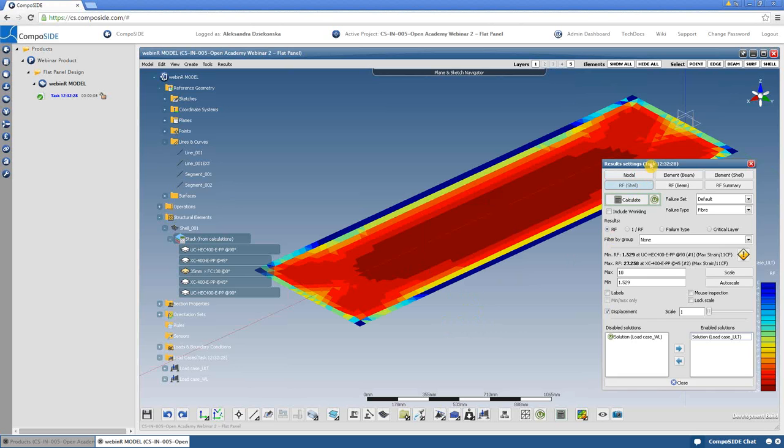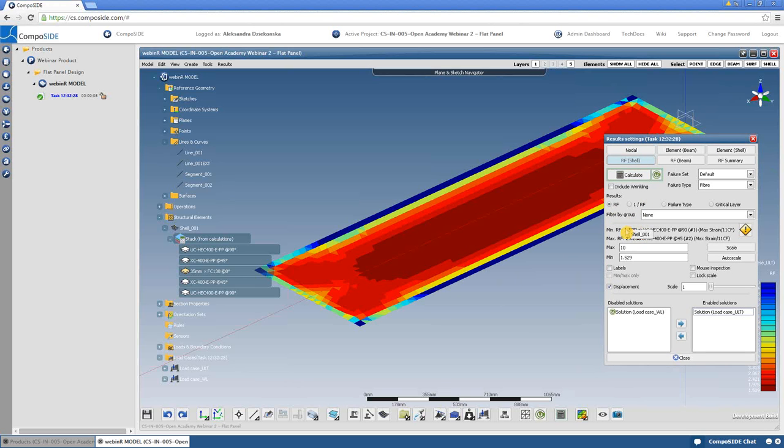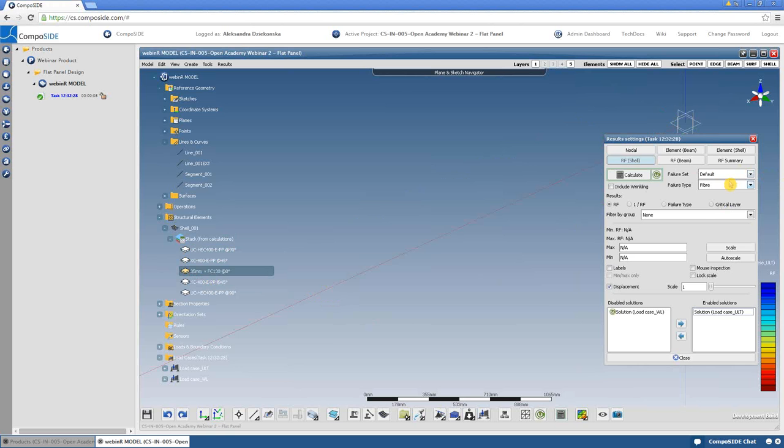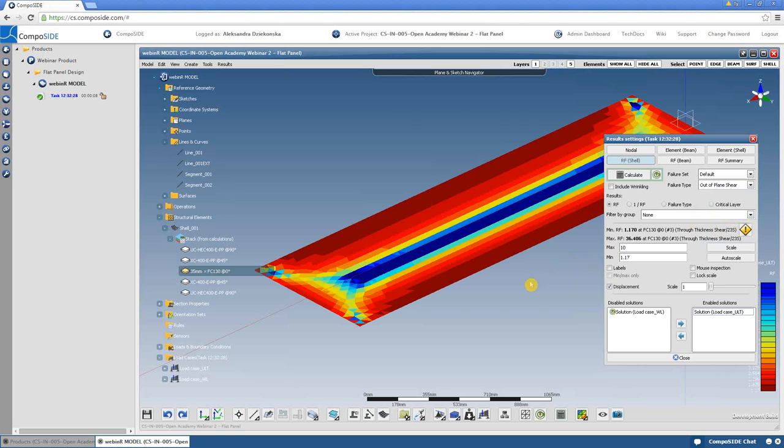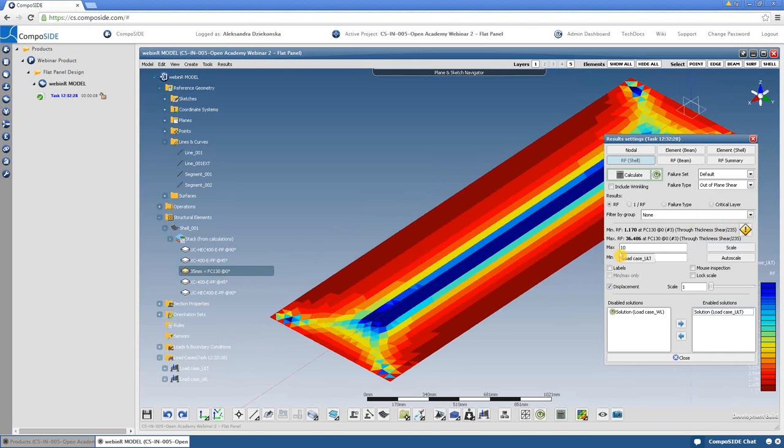Okay. Yeah, looks good. We are good on the fiber failure. It's 1.5, which matches what we did on Lamina. Now you can see that we have envelope results for all the plies and for all stacks for this particular shell. We also can change the failure settings, but what we are going to do is select only core to check the out of plane shear reserve factors, and that shows us 1.17, which also matches quite well our results from Lamina, and basically allows you